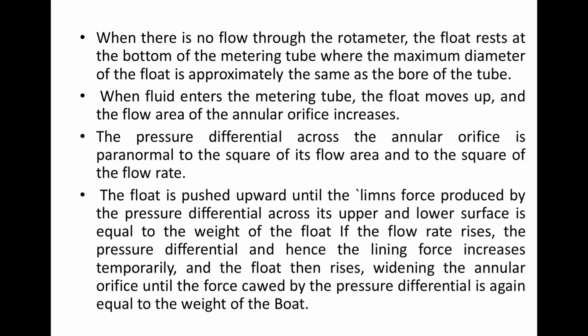As seen already, three positions. And here, the maximum diameter of the float is approximately the same as the bore of the tube. When the float is at the bottom, the maximum diameter is the same as the bore of the tube, that is, the inside diameter. So when the fluid enters the tube, the float moves up and the flow area of the annular orifice also increases.